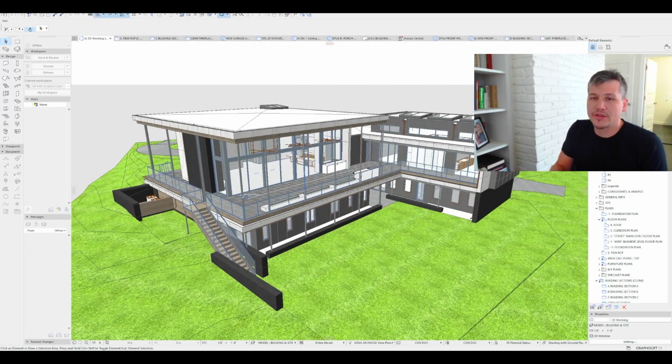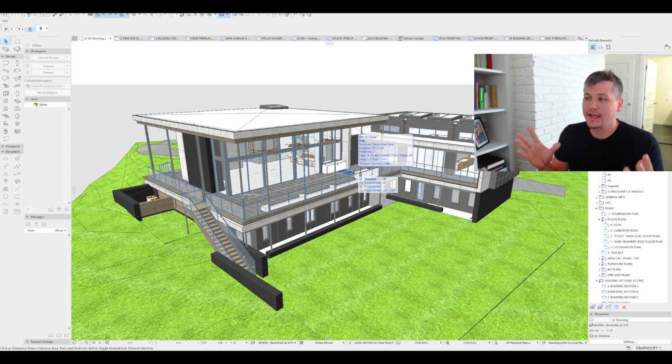So doing that structural evaluation is going to be important not only for the lateral resistance, but you're also going to start figuring out how big some of the floor systems need to be. On any modern home, you're going to have issues when it comes to running ductwork. And the way we solve that in most cases is we use floor trusses to allow us to put horizontal chases in those floor trusses and provide a space for the ductwork to go.